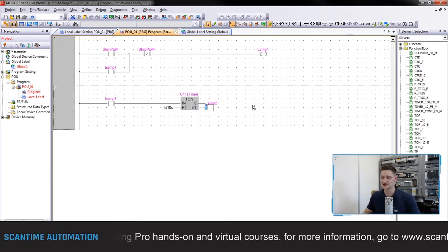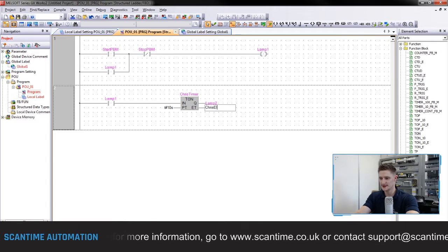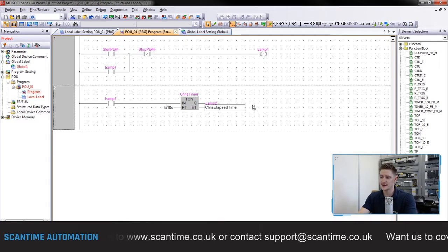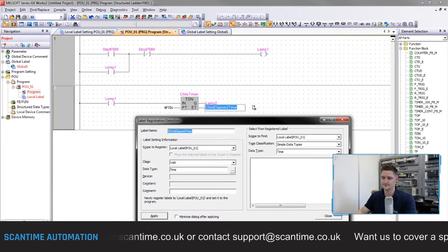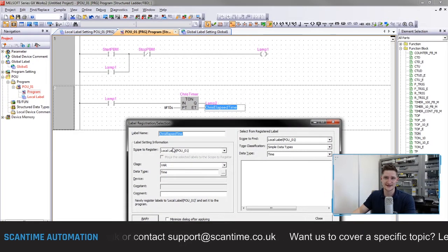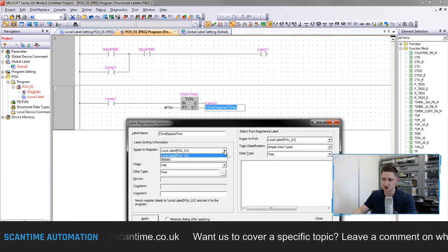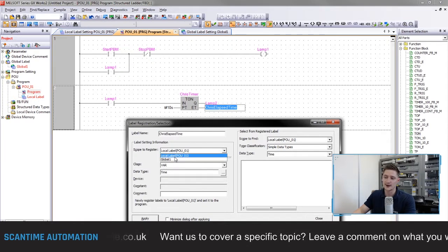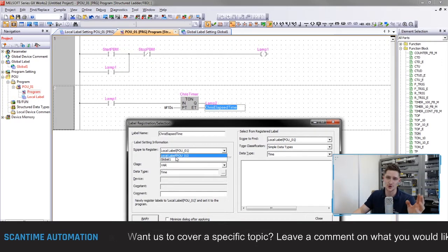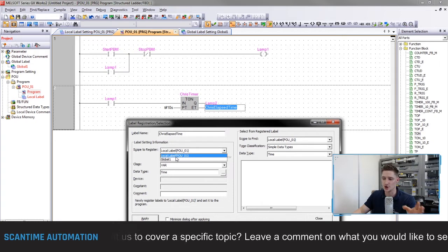So for me to create this as a local label, I can just give this any name. So I can call this Chris elapsed time and then press enter. And what will then ask me to do is again assign this to a register inside of our local labels register. If I want to assign it to my globals, all I do is drop this down and select global, but I want to assign this to the local label because it's only going to be used inside of POU1 only.